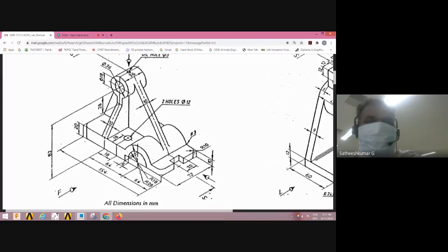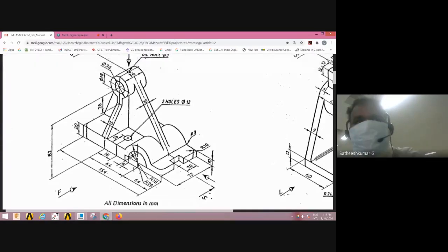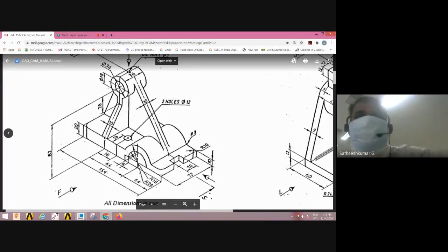And there is a mound-like feature which has a radius of 18 on the inside and 28 on the outside diameter. Above it there is a vertical feature holding a cylinder in the horizontal direction. The length of the cylinder is 36 and the diameter is again 36 and the internal hole diameter is 18.